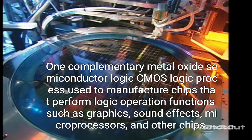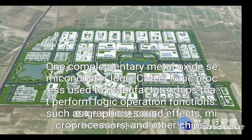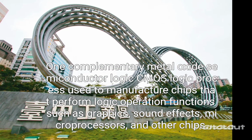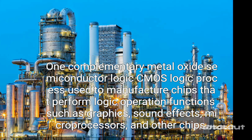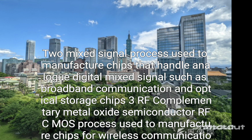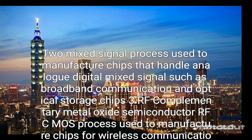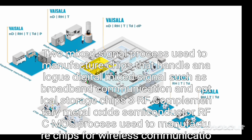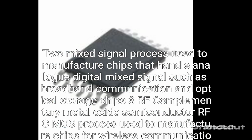1. Complementary metal oxide semiconductor logic, CMOS logic, process, used to manufacture chips that perform logic operation functions, such as graphics, sound effects, microprocessors and other chips. 2. Mixed signal process, used to manufacture chips that handle analog, digital mixed signal, such as broadband communication and optical storage chips. 3. RF complementary metal oxide semiconductor, RF CMOS, process, used to manufacture chips for wireless communication, such as chips for mobile phones, wireless local area networks, WLAN, and Bluetooth.